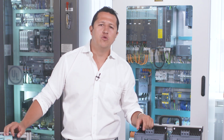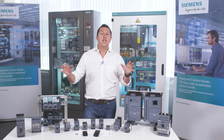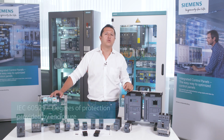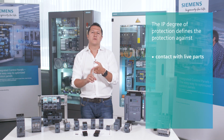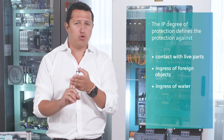When we talk about this type of protections, there are often two standards used worldwide for classifying the degrees of protection. For international markets, we use the IEC standards. Let me show you how. The IP degrees of protection are based on the requirements of the international standard IEC 60529 and indicate the suitability of electrical equipment with regard to use under various environmental conditions. The IP degree of protection defines the protection against contact with live parts, ingress of foreign objects, ingress of water inside or into the enclosure.